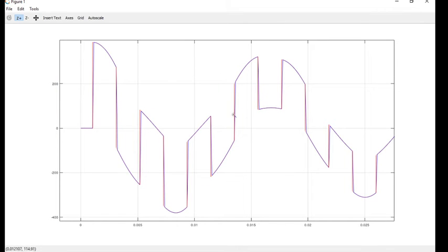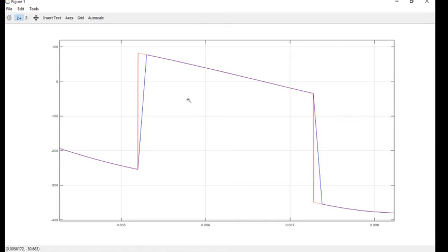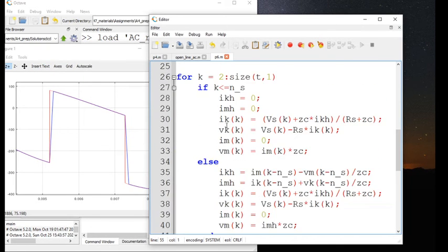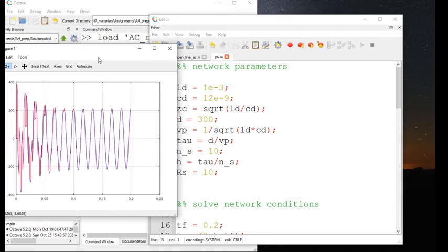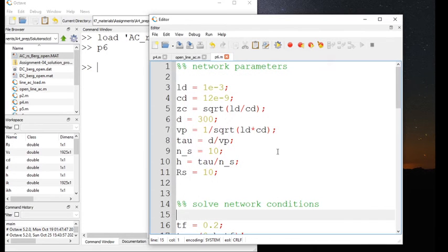Fine, so whatever you simulate, it doesn't diverge so much, but the difference you see here, can you help me with why it's happening? Yeah, it's merely due to the step size. Step size here in the R code is of the order of 0.1 millisecond, and here we have chosen 1 microsecond. If you want, let me set that.